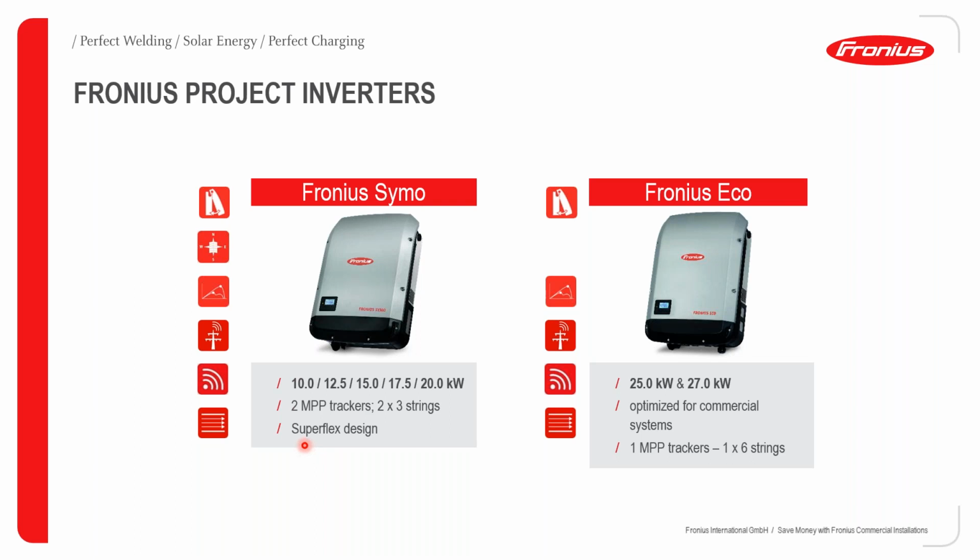Talking more about the Superflex design, there are inverters that are designed to carry equal capacity on both MPP trackers. So some are designed for 50-50 purposes, while some are designed to carry more power or more capacity on one MPP than the other.